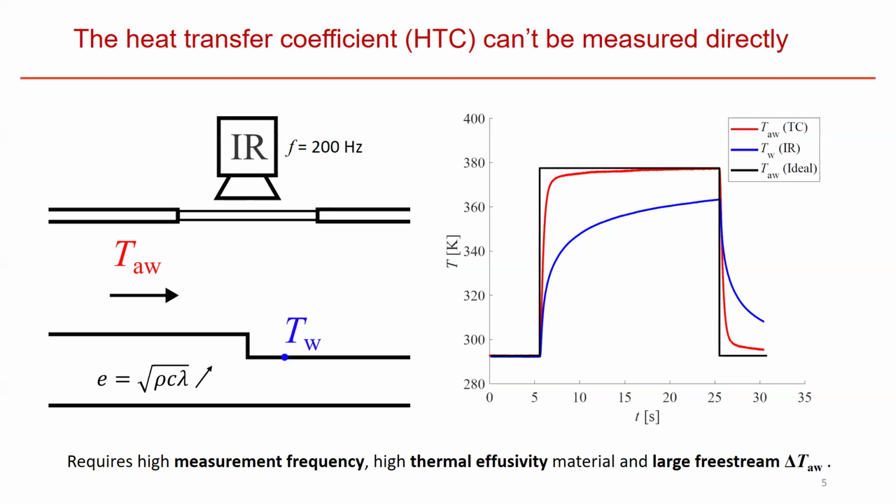And this is really important because this essentially means that heat transfer experiments are usually small scale. Because to give you numbers, if you want a 30 Kelvin temperature step for a mass flow of 1 kilogram a second, that's already 30 kilowatts. That is quite a small domain, 1 kilogram a second. So yeah, it's important that we can conduct these experiments at small scale.